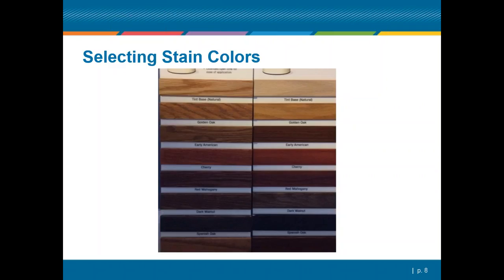An example would be if we were using a prime coat in a paint system. We normally don't leave those prime coats uncovered because primers are made up in a little different manner, and they don't have the same wear and tear consistency that the finishes do. So we put the primer down, and then we put the two finish coats over the top of that. The same way with these wood systems, we put the stain down to achieve the color degree that we want, and then we put the varnishes or polyurethanes or any other products over the top of those to give us the protective value to the wood. I hope that answers the question.